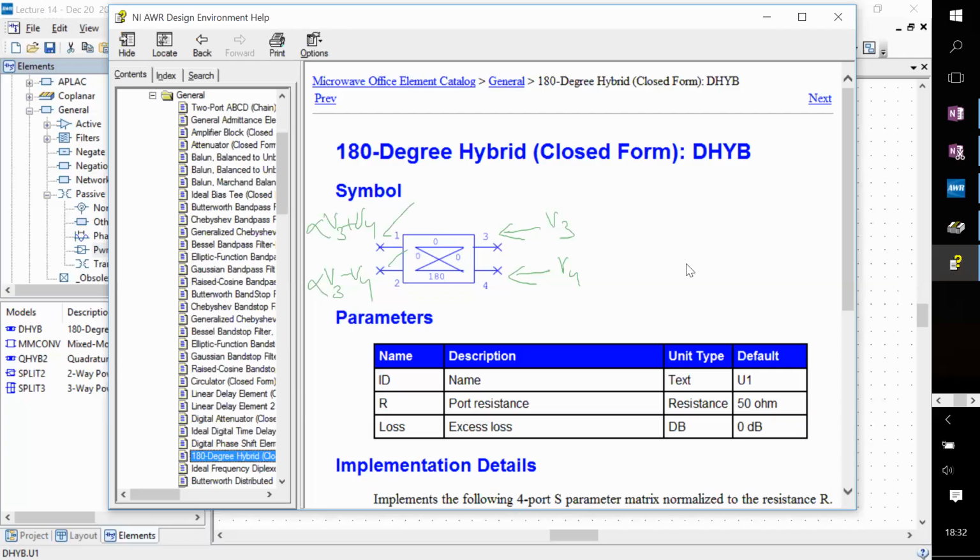And this conversion from even to odd mode and those kinds of things can happen depending on the boundary condition. You might have excited the even mode and signals go out here, but maybe you did something where this signal returned with a +1 gamma, but this one returned with a -1 gamma. And you have now turned an even mode excitation into an odd mode excitation. And now it's going to come out of somewhere else. So we can actually check some of these things now.